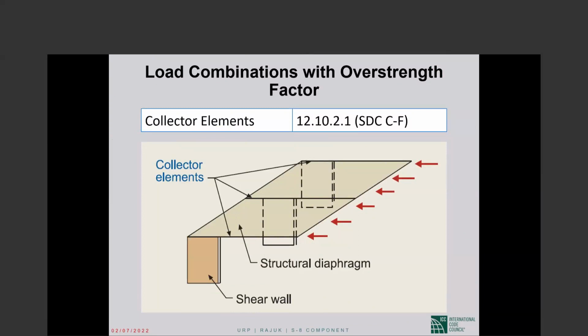Okay. Now let us explain that. So this is a slab acting as a diaphragm. A slab acted upon by bilateral loads which will cause in-plane bending. So you are looking at compression on this face, tension on that face, and shears along the side faces. Those shears have to be transferred to supporting elements, shear walls or frames. Now, if that shear wall were supporting the entire edge of the diaphragm, there would be no collector.